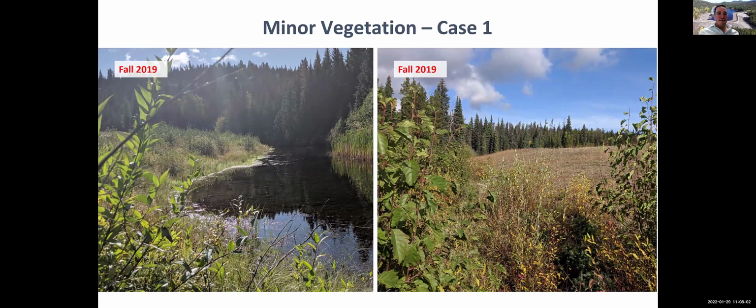So the photo on the left, basically I'm standing in the middle of the downstream slope. Looking toward the way the water flows, I look to my left, there's a toe seepage pond. You can see quite a bit of vegetation growth there. It's quite wet, soppy, so you get a lot more aquatic type vegetation growing there. And then you turn to the right, I'm kind of standing in vegetation, trying to look and find things. There's actually a larger toe pond that's obscured from the view on the right side.